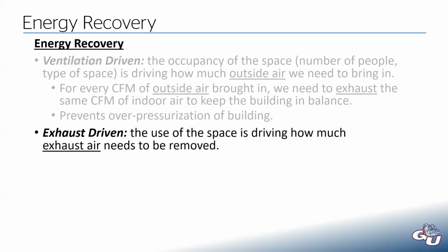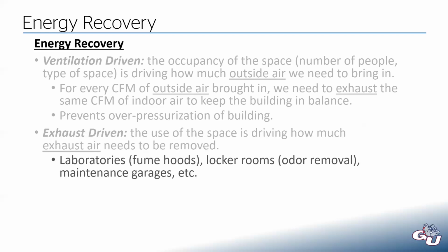An exhaust driven system is based on the use of the space and how much exhaust air we have to take out of it. Some examples would be laboratories. If you have those fume hoods exhausting all kinds of air, if you're working with chemicals and things like that, or if you have a locker room, you want to remove those odors, or a large restroom, same thing.